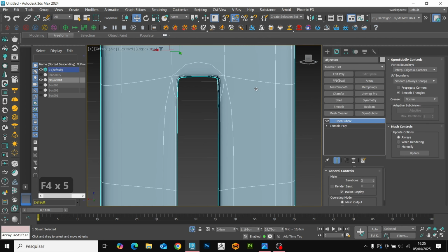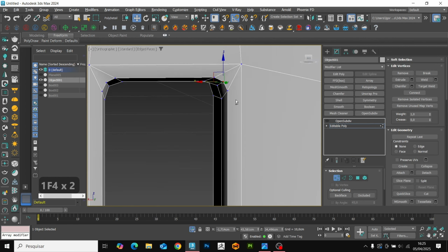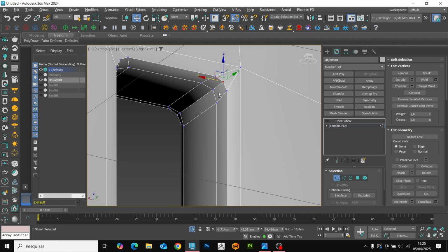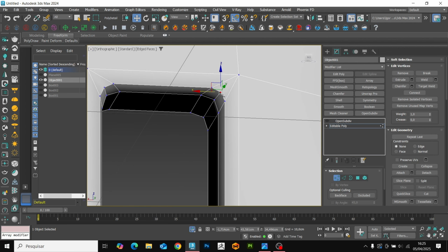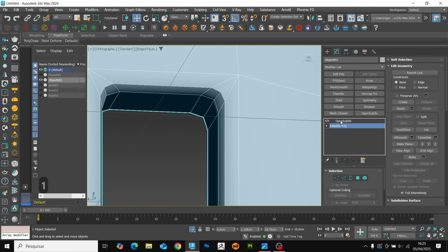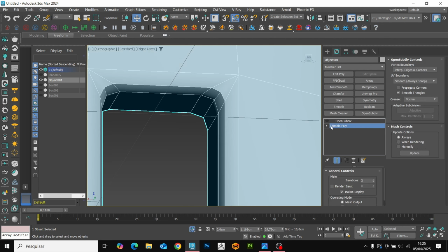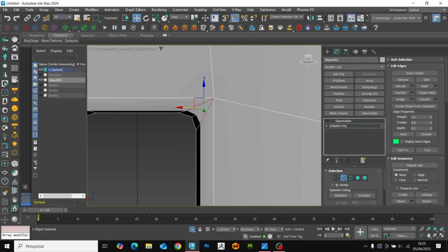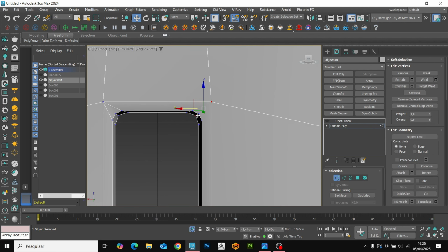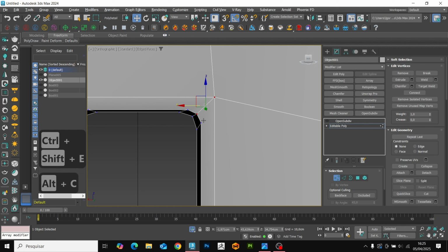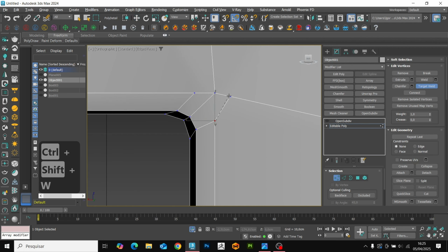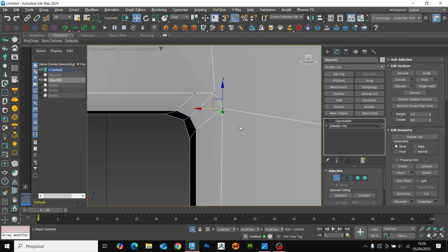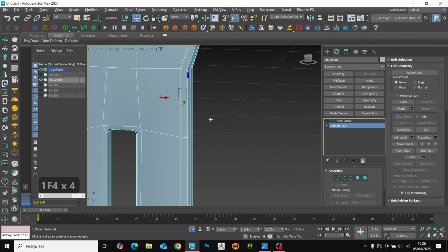Now we add the Open Subdivide modifier, and here we see that we have a small problem at the back of the model, where we have a face that has become triangulated, so we will solve it by adjusting the mesh. I'm going to remove some edges and reconnect the mesh using tools like Cut and Connect, as well as Target Weld and Collapse. We are going to link the new face to the top face and then use the mirror to mirror the shape.